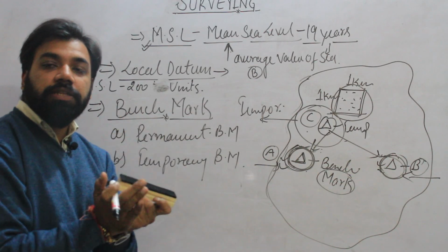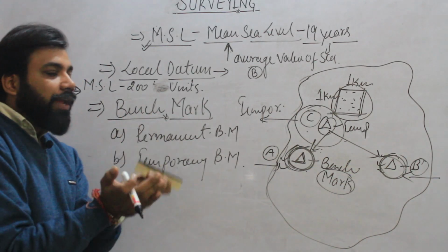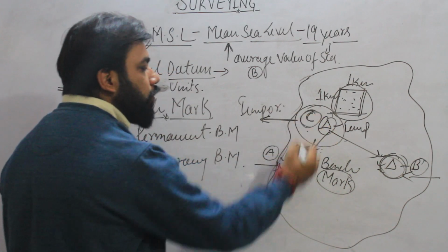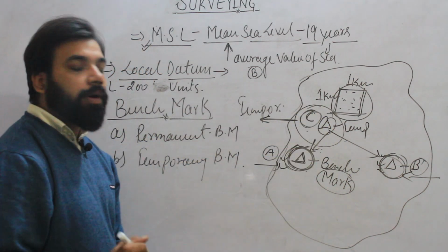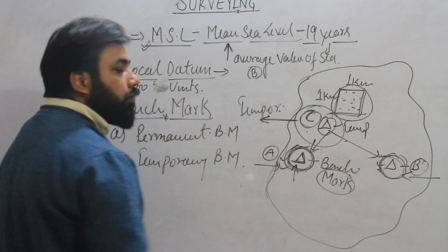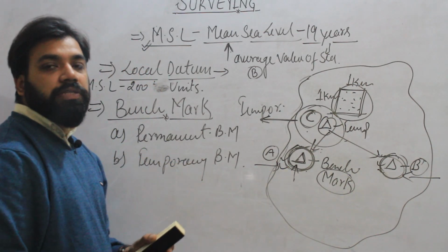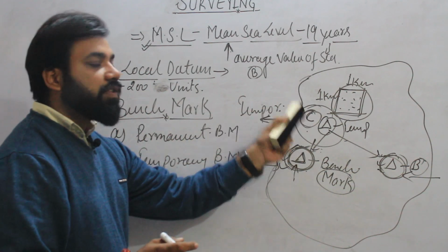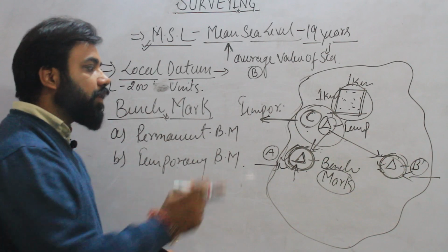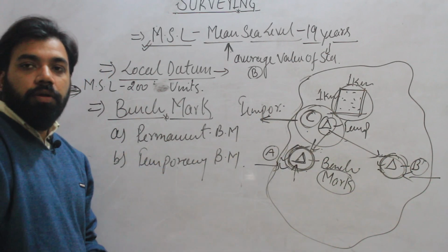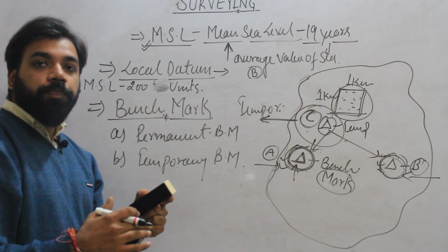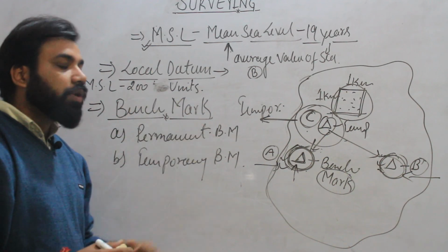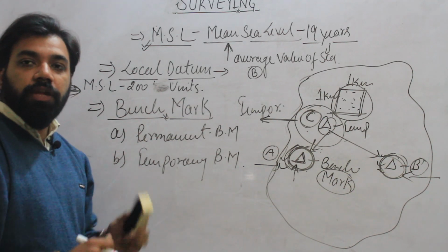For completing the work of a small area of survey, we establish a new benchmark with respect to the permanent benchmark, whose height is accurately measured with respect to the mean sea level. We do not refer again and again to the mean sea level for short work. That's why we establish these benchmarks, and permanent benchmarks are established throughout the country with respect to the mean sea level.